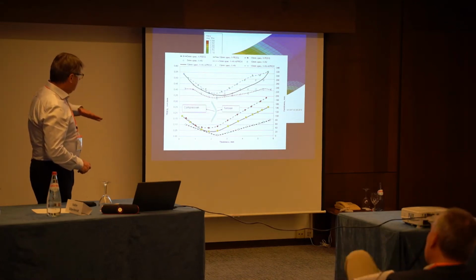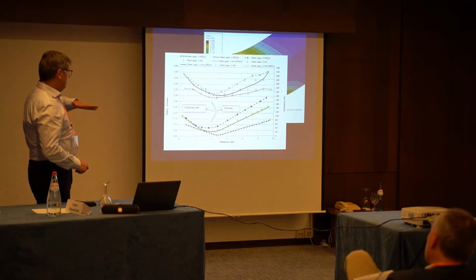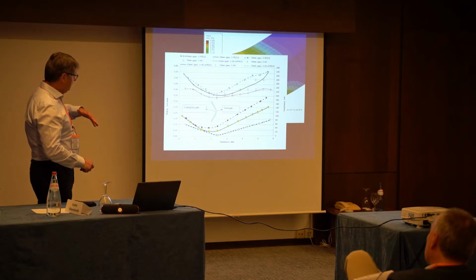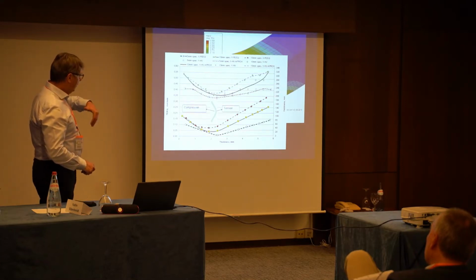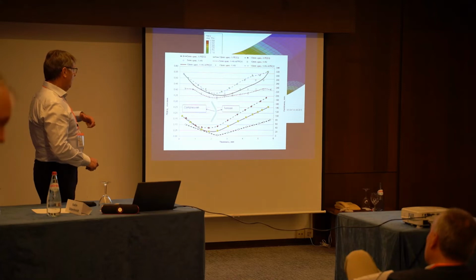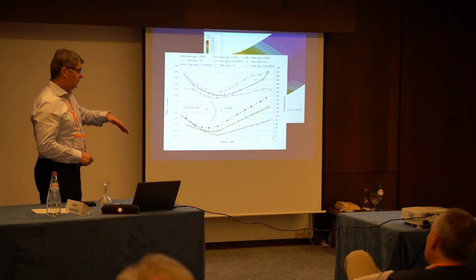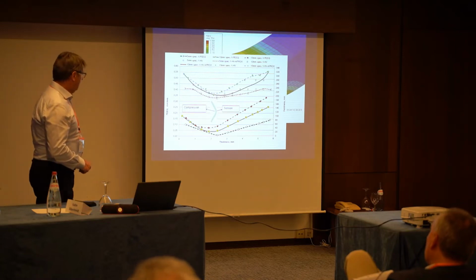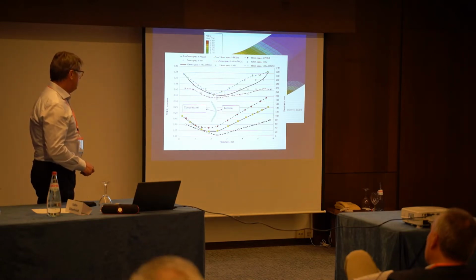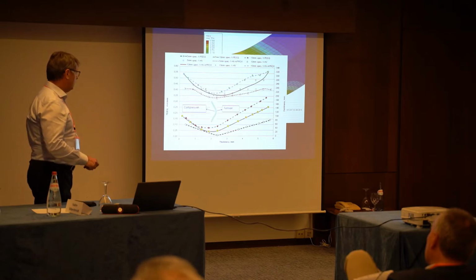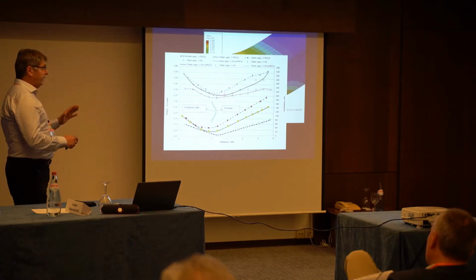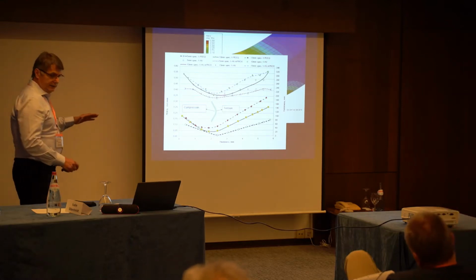So now we have correlation between compression and tension, because the tension is on the steep side, this one, and here on the envelope side we have the compression during the bending. But you can see that the equivalent stress is in the same range on the compression and tension sides. Of course, in the tension you have the higher equivalent stress on this side. So now we have some correlation between stress and hardness.